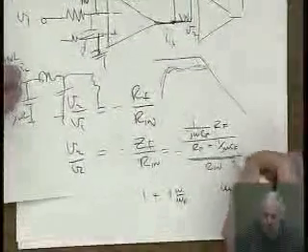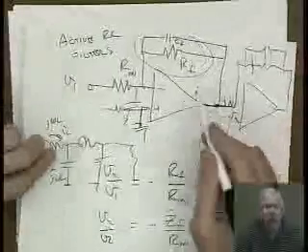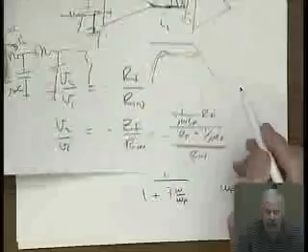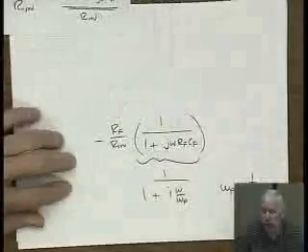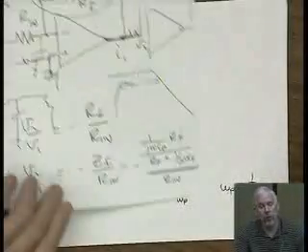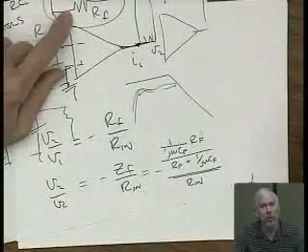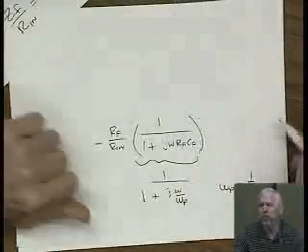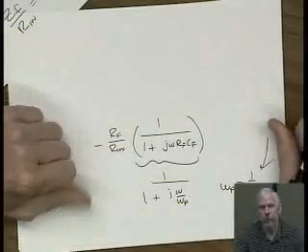What's wrong with this approach right here, this RF-CF thing? So the pole was at 1 over RF-CF. If we want to put this all onto a chip, if we want to do a fully integrated active RC filter on a chip, what's the problem? What are the problems?